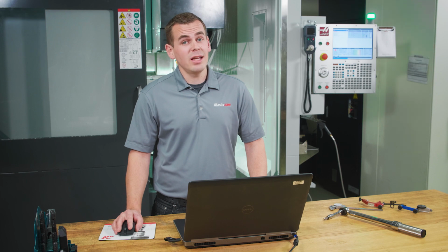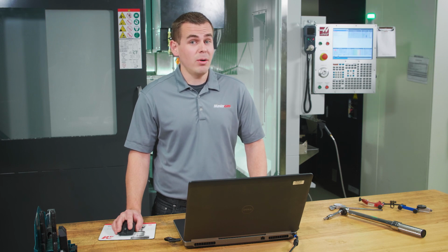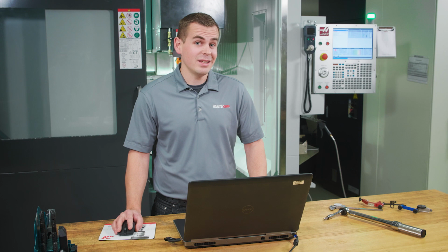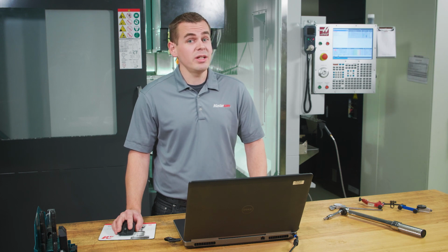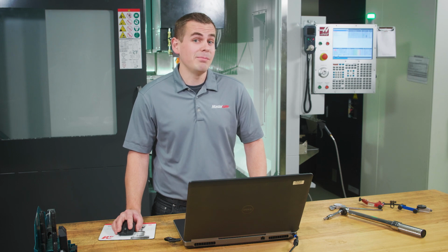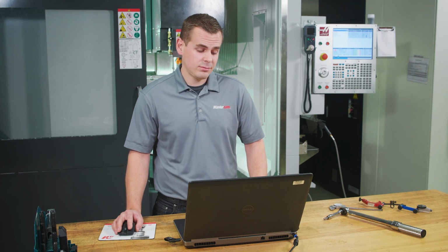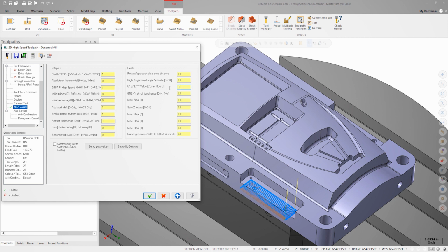If you're not using dynamic toolpaths and have sharp corners in the part where the machine must accelerate and decelerate quickly, this larger E value will certainly help make the machine produce a smoother transition and maintain feed rate.